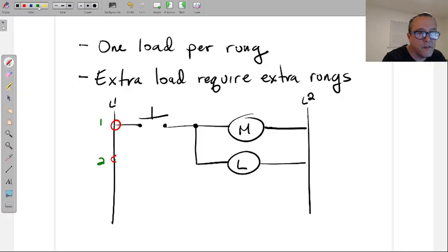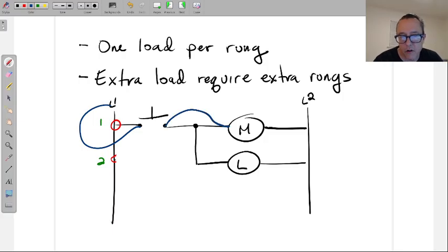When I'm wiring this up and I'm starting to bring my wires from L1, I bring a wire from L1, terminate it at the push button, bring a wire from the push button, terminate it at the motor starter, A1. We'll start to throw in some numbers now. This is universal for all motor starters. No matter the brand, everyone uses A1, A2. So what do I do with this wire? Well, this wire's got to go to one of those two spots.